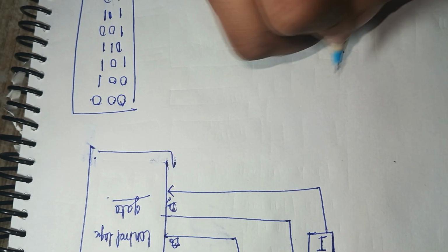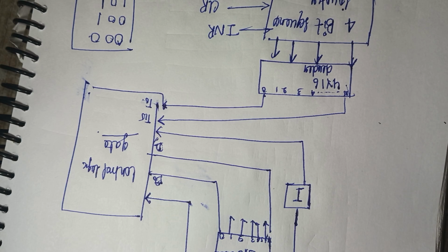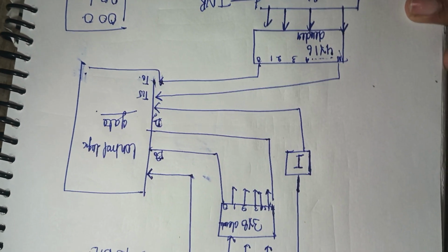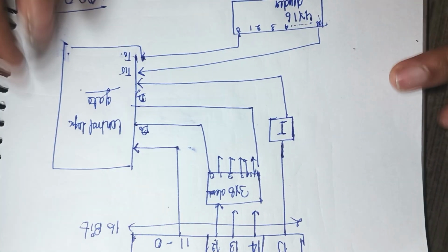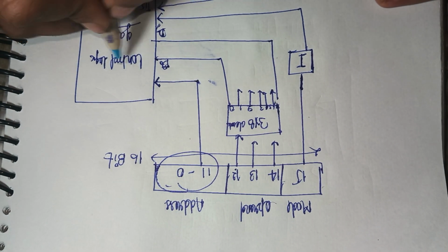Then after the last signals, that is the signals of the timing pulses from T0 to T15, which are generated using a 4 into 16 decoder. The first 12 bits are applied to the control logic.